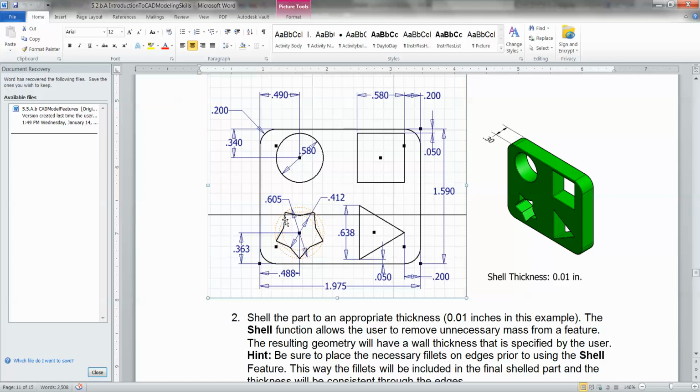Now, there is a little bit of a tilt to our pentagon that is separate from our other shape. I'm not going to worry about that at this time. We don't have specific dimensions on that, an angle or another constraint. So we're going to simply leave that in there, and we're going to start drawing this star pattern, which is going to start in the corners of the pentagons, come down to the circle, and back over to the corners. Now all these lines are the same length. We're going to adjust that after we draw them.